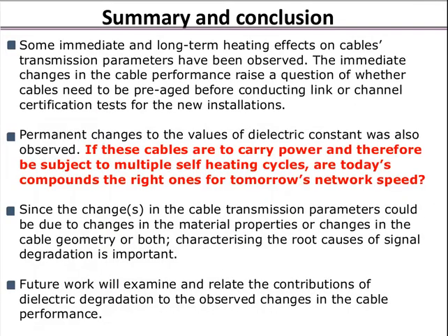In summary and in conclusion, some immediate and long-term heating effects on cables' transmission parameters have been observed. The immediate changes in the cable performance raise a question of whether the cables need to be pre-aged before conducting link or channel certification tests for the new installations. Permanent changes to the value of dielectric constant were also observed.